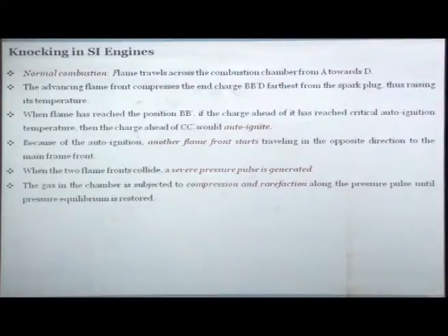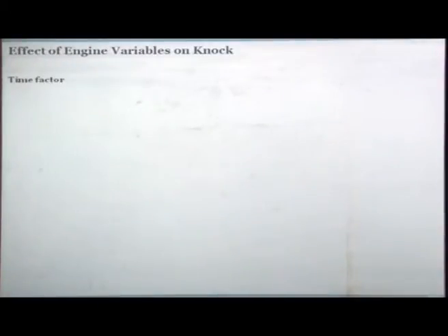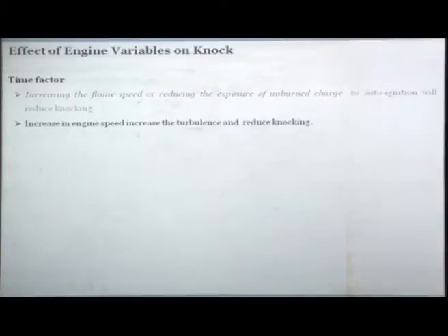When the knocking happens, there are two flame fronts, they collide, severe pressure pulses are generated, and then these pressure pulses get reflected between the piston and the cylinder head. That's what causes the vibrations. So let's look at some of the factors.